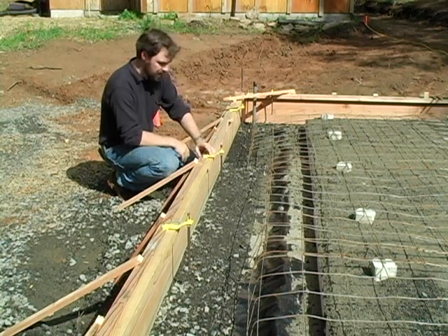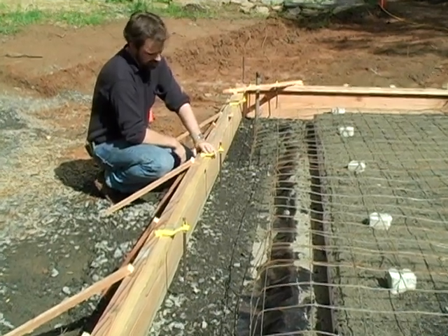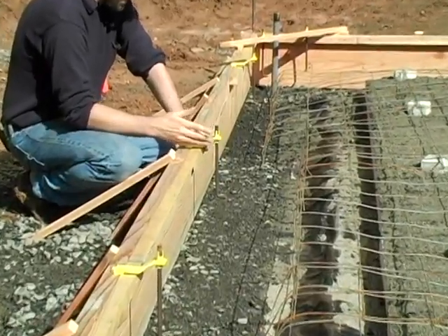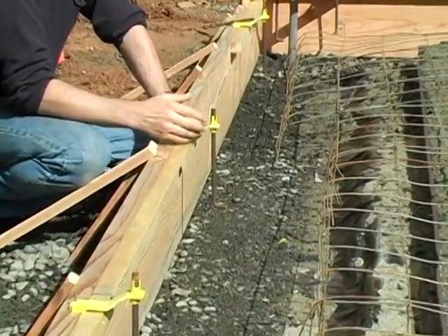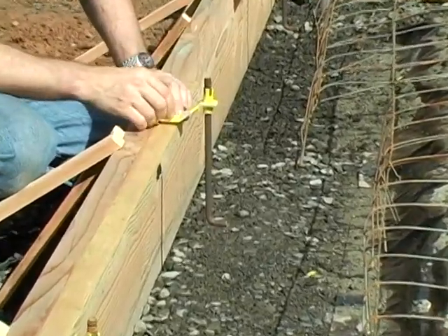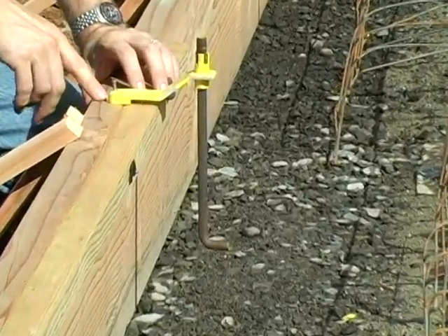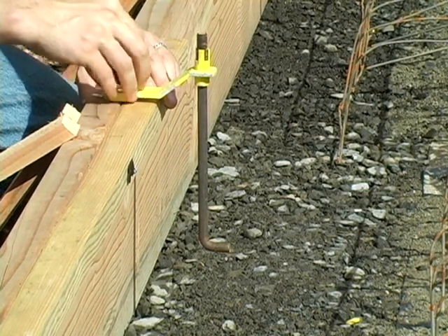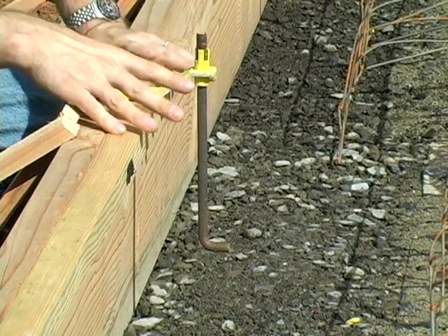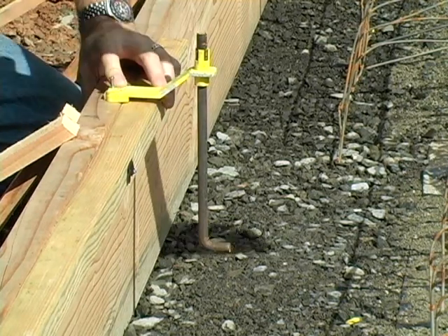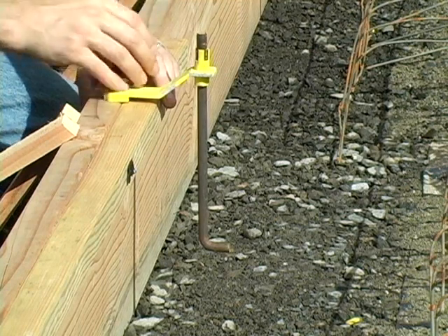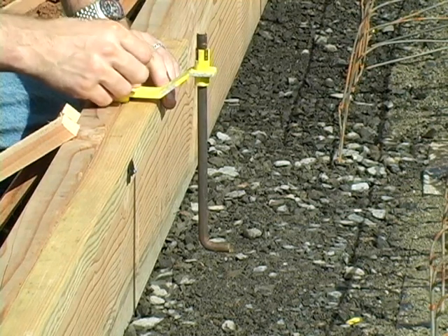Now, I'm using here what's called an anchor mate. There's a number of different ways to do this. You could do it just with some scrap wood. I like the anchor mate because it's designed specifically to give me a certain offset and hang my bolt at a certain height. So the idea here is I set this right in place, and now I don't have to hand place any of the bolts around the building. Again, this is a load-bearing straw bale. I'm going to have another plate on the inside, which I'll have to hand place those bolts. So this just eliminates half the work for me before the pour begins.